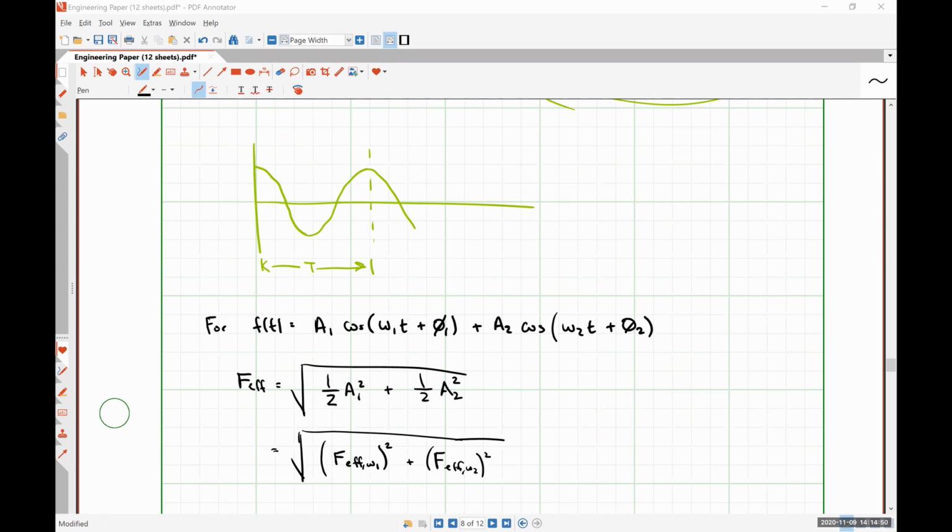One thing that I want to point out here on problem 2, in parts D and E, you're asked to calculate the power absorbed by ZL, etc. And it's specifically asking for the complex power, okay? Notice that the voltage that is given here is not in units of volts RMS.